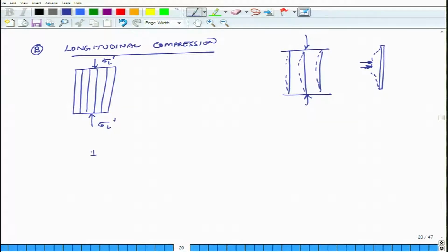So, if Vf is small, then the fibers will do micro buckling, even if the material is in the elastic range, because there is a lot of matrix and the matrix can take in a lot of forces, because the amount of matrix involved is large.